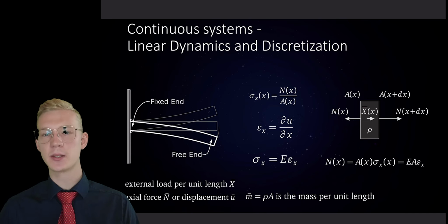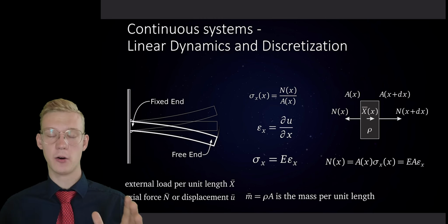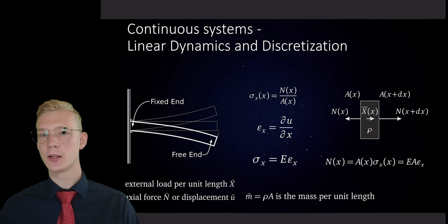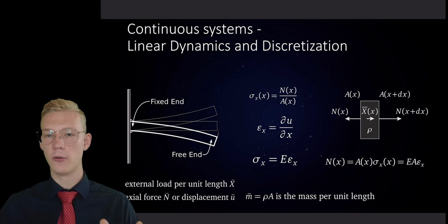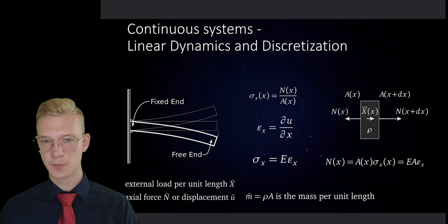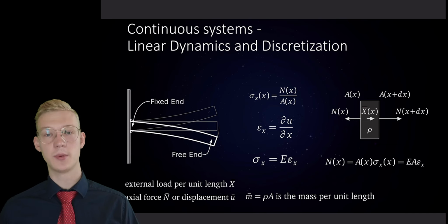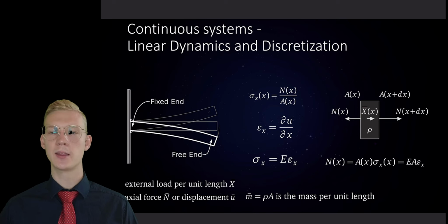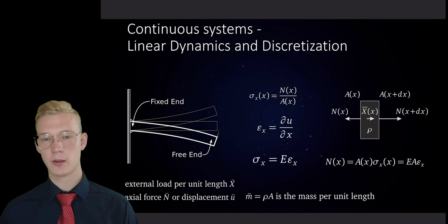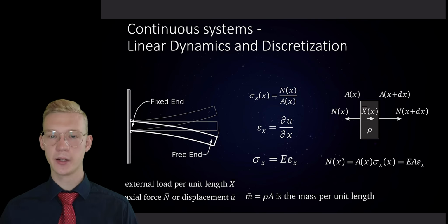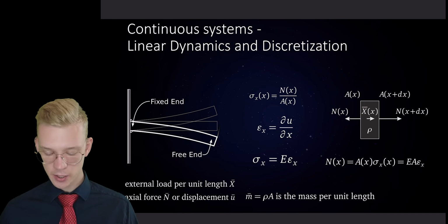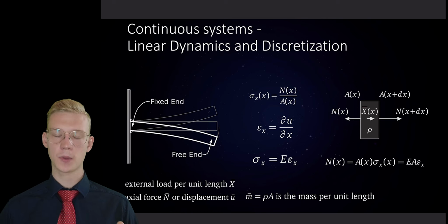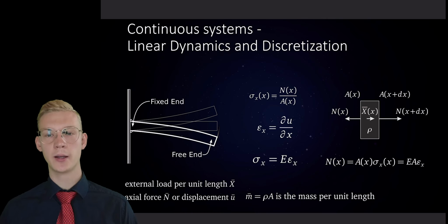So a continuous system is basically an infinity of masses combined together. So we technically would find also an infinity of eigenfrequencies and eigenshapes. This cannot always be done analytically, so we will need some method to discretize our system again and get the eigenfrequencies and eigenvalues. But for some solutions, for example, like with the bar, we will get analytical solutions of those eigenfrequencies and eigenvectors. So let's start with a simple bar example of a continuous system where we will find the